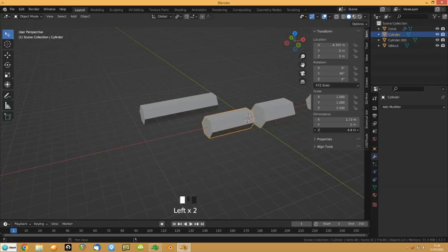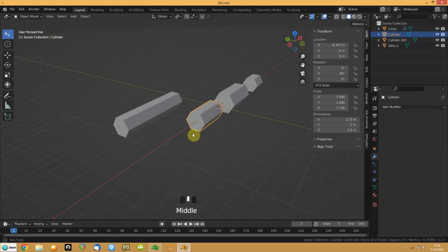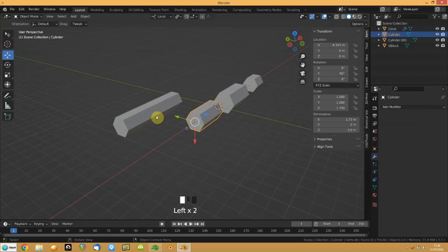You see, I'm saying scale on the Z axis, but it's moving it up on the X axis because it's been rotated. Same there, so you have to bear that in mind. And the reason you tend to apply the rotation is then you say, okay, what if I want to scale on this axis, which is the global Z? The only way to start figuring that out is to change that to local, and say, okay, you've got to scale it on the X axis.